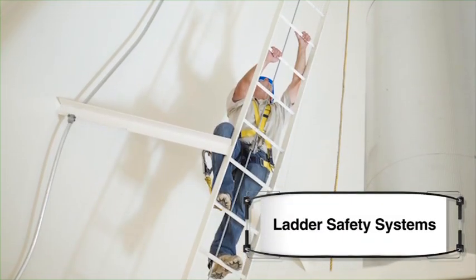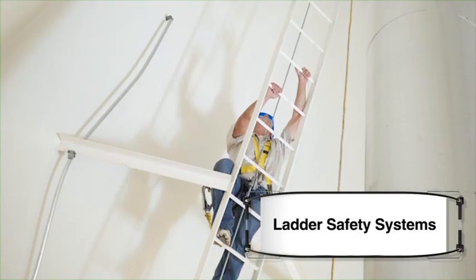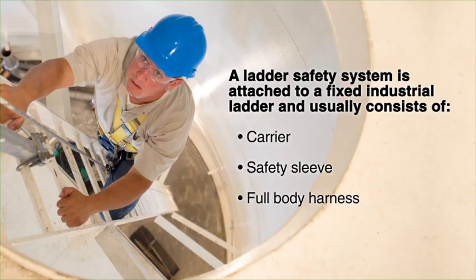A ladder safety system is designed to eliminate or reduce the possibility of a worker falling off the ladder. A ladder safety system is attached to a fixed industrial ladder and usually consists of a carrier, which is typically a cable that runs the entire length of the ladder, held on by mounting brackets at the top and bottom of the ladder, and a safety sleeve, which is a device that attaches to the worker's frontal attachment on his full body harness.